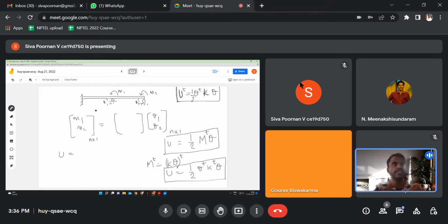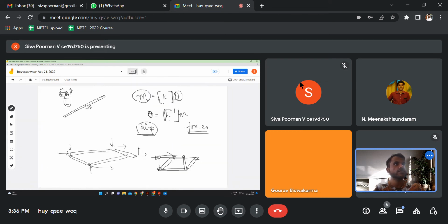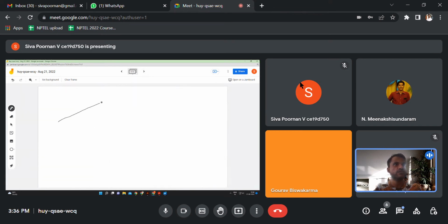So you can have a truss oriented at an angle, and now the displacements can happen anywhere. You can take this nodal point like this and then like this, from here to here. So there can be a u1 displacement degree of freedom, a u2 degree of freedom, and then you can also have u3 and u4. So this is movement in a 2D plane.